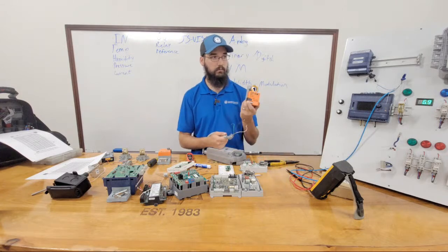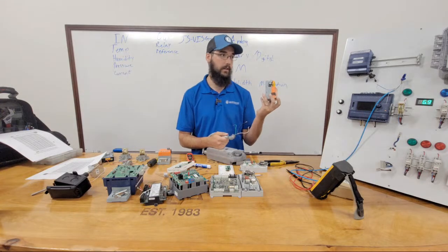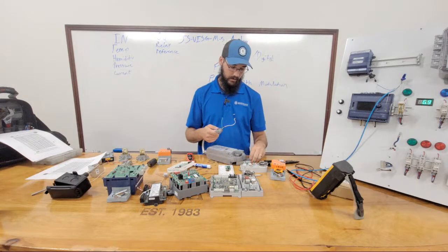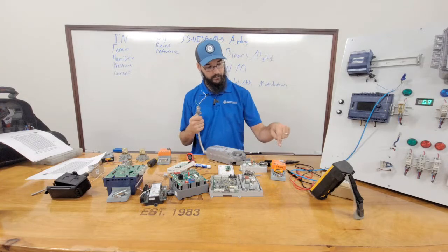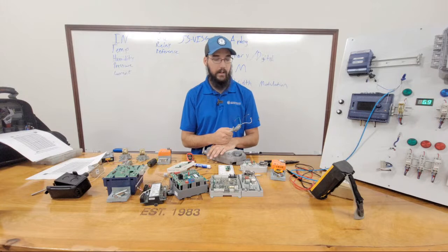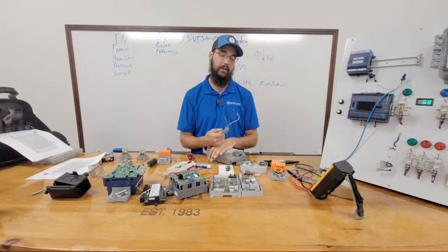Whereas, I guess technically we only need one binary output with this, but a lot more wiring goes into this. This thing's a lot smarter, a lot higher failure point. The other factor is this loses power, it doesn't close. In a fire situation, you need any air source to be able to close. That's why they use these on fire dampers to begin with.